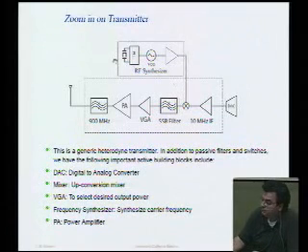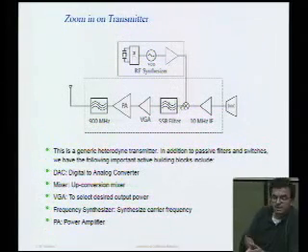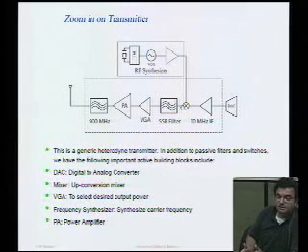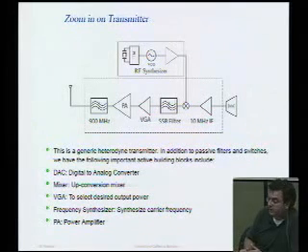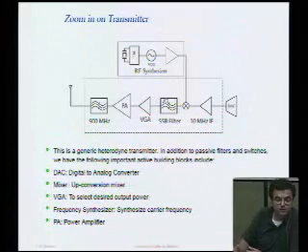There's that little crystal symbol that somebody brought up. This is our precise reference frequency. So now we've translated our baseband signal, the bits, into a precise RF signal, very precise frequency. And we can also set the amplitude very precisely with, let's say, a VGA, a variable gain amplifier. And finally, we run that into a power amplifier.